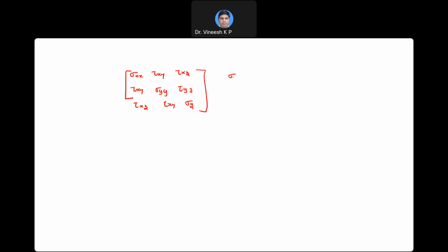So sigma xx indicates that in Abaqus, the x-axis is 1, so it is going to be 1, 1. Basically, the stress notation in Abaqus is such that this is going to represent S11. So sigma xx is going to represent S11. In this case, we will have only sigma 11 as well as von Mises stress. Y-axis and z-axis stress will be equal to 0.